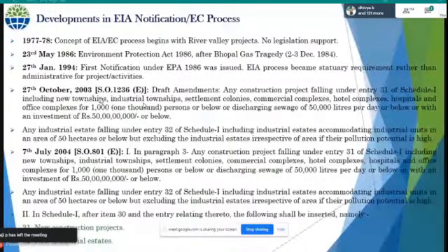there was one amendment to that having 3 attributes. One is having more than 1,000 employees in any commercial complex or hotel complex or hotel or settlement colony or industrial area, that is known as township area development. So that is also included. And if any township is discharging more than 50 KLD, then again they have to procure environmental clearance under the EIA notification. Otherwise, if they have more than 50 crores at that time, then they have to come under the EIA notification 1994. But now it is 250 crores. This means the notification had a provision of 50 crore. If investment is